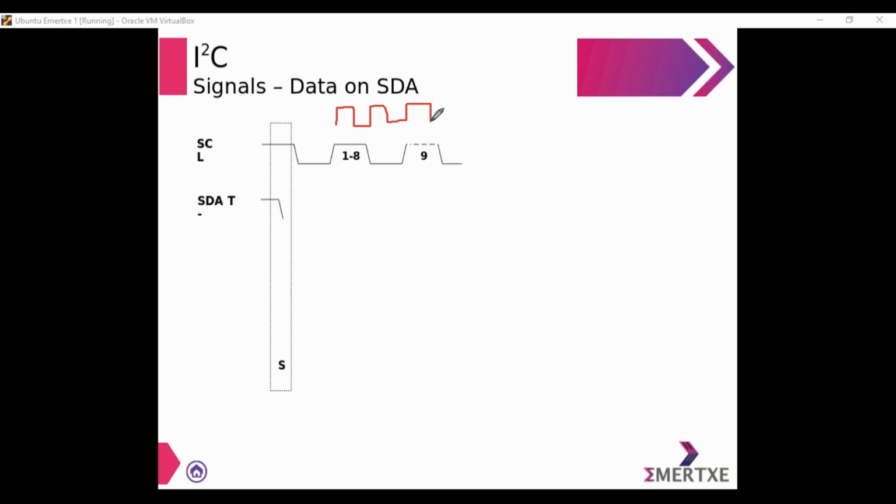So 8 clock pulses get generated like this. Now the first task is for the master to start the communication. Assume the master is done giving the unique address of the RTC, and assume the slave is done giving the acknowledgement to the master. So my next step is, the master should transmit the second register's address.